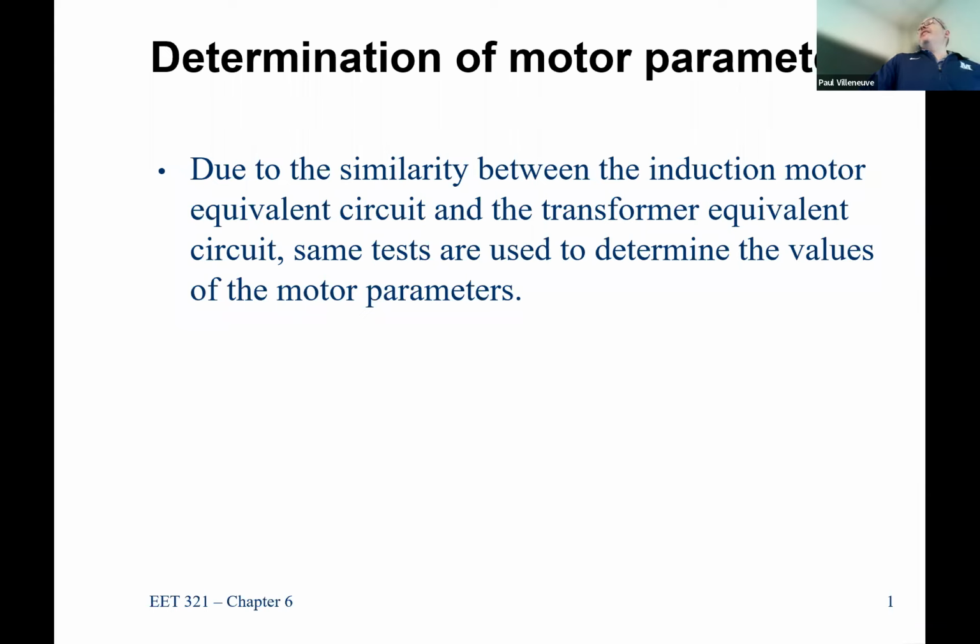The analogy here is we want as much load as possible on this thing. How do you get as much load on an induction machine? You take a chain, wrap it around the shaft, tie it into place, and don't let it move. It's called the locked or blocked rotor test.